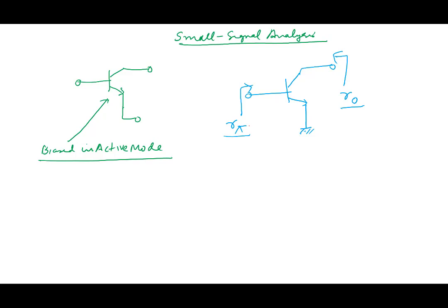Suppose I modify this to the following. This is important for us. I add here, what is the resistance looking from here? Let's say this is RE. These are all small signal. Never forget that. What is the resistance looking from here? R pi, or if you want to be more accurate, 1 plus beta times RE. Whatever is the resistance here, when you look from here, it gets multiplied by 1 plus beta. Okay?